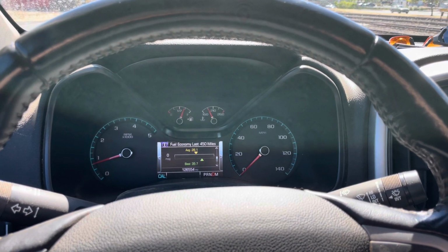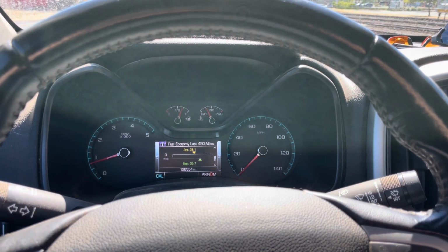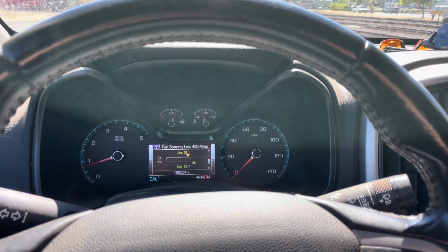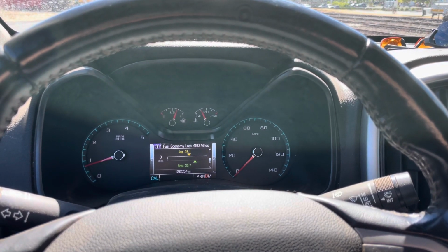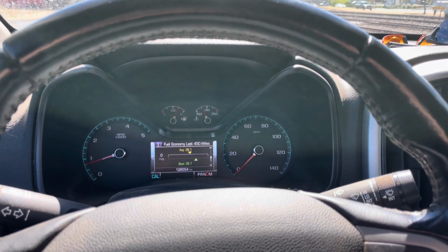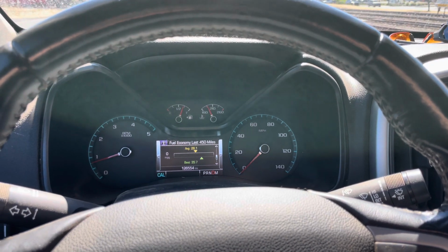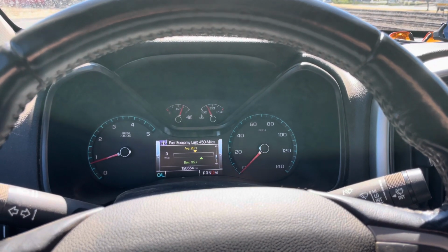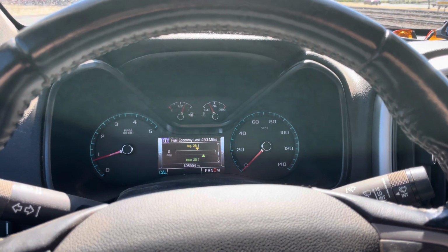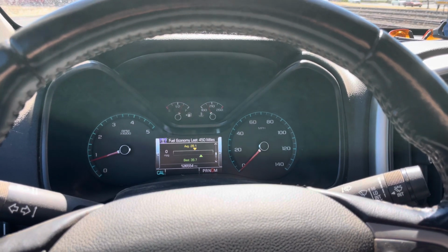Okay, so I decided to take a quick drive up the road to get up to temperature. I made it about 500 feet and the message went away. So sometimes all it takes is to take it for a drive. You're going to meet those conditions for running a self-test. The self-test will run, pass, and the message will go away. So I no longer need to do the tamper test to clear the message. The vehicle is now fixed. Let's go talk about the pump real quick in our summary, and then we're done.